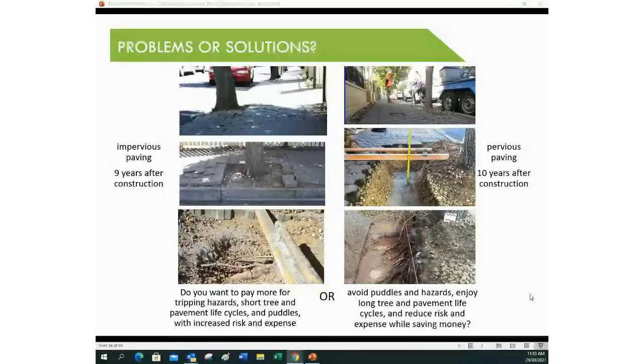Use permeable paving wherever you like, but specifically target the places people will walk. You can also build it level. You don't need a crossfall. So all those kids going to school don't need spinal problems down the track because we put a 4% grade on the path they walk down twice a day. So have a think about that.